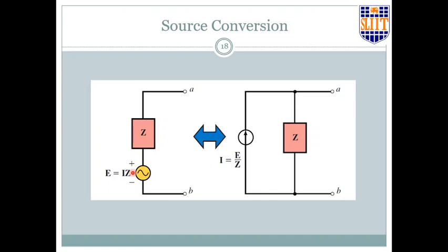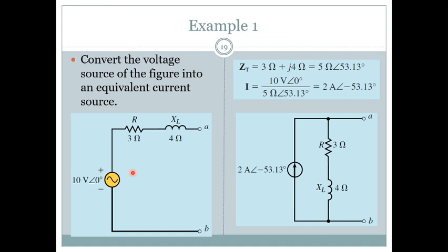So we'll have to use the complex number domain in the calculator for these calculations, and all these values will be in the complex number domain because they have a magnitude and a phase angle. Again, I'm reminding the point that there is no imaginary current values or voltage values. They are very real, but because they have a phase angle to be represented, we use the complex number domain, right?